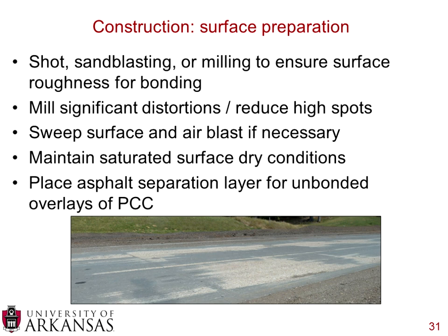Now we're working with concrete here, and concrete needs water to hydrate. Something that can happen is if you put a concrete material on a bone-dry surface, water will wick down into that surface, and you'll lose water from your concrete paste, and you'll have problems with your hydration. So you want to maintain the saturated surface dry condition. And what that means is you don't want pooled water, you don't want water standing on your roadway, but you want water to be immediately under that surface. So the surface doesn't have standing water, but immediately under that surface you do have water, and that will prevent water from wicking down into the existing pavement.